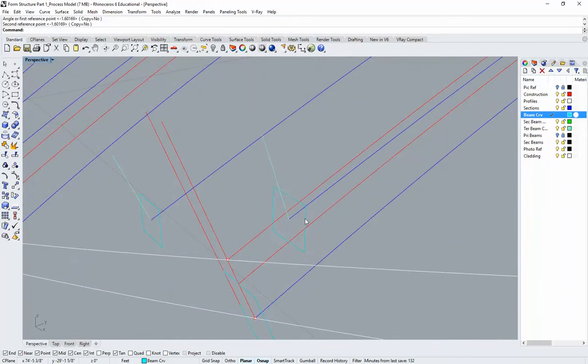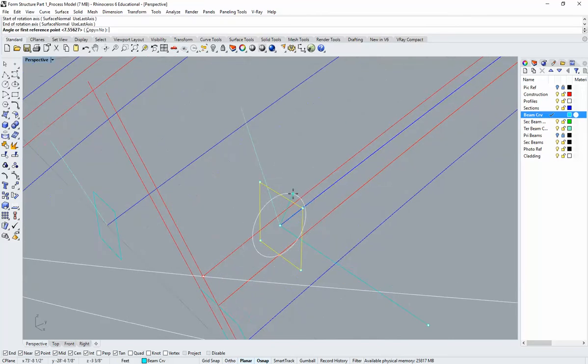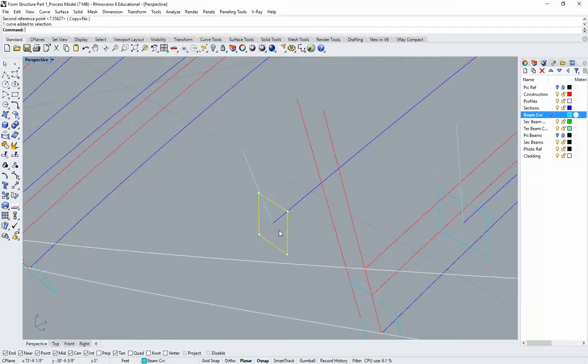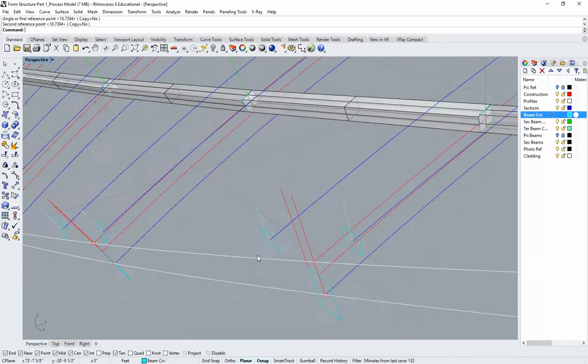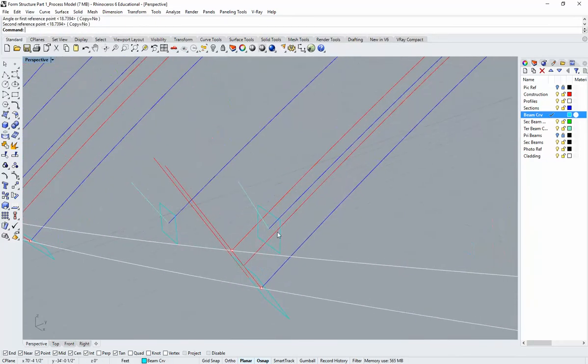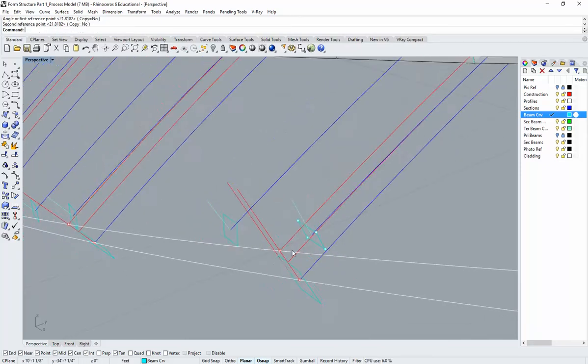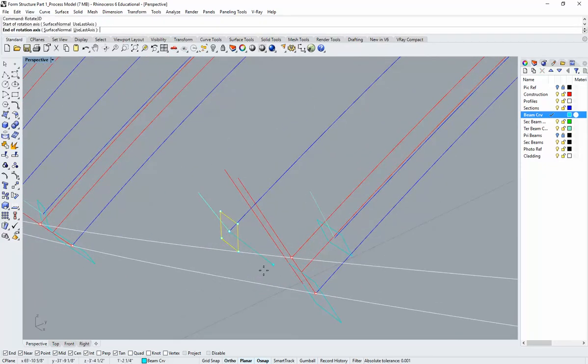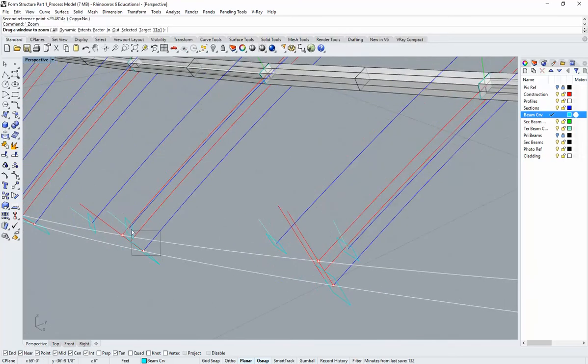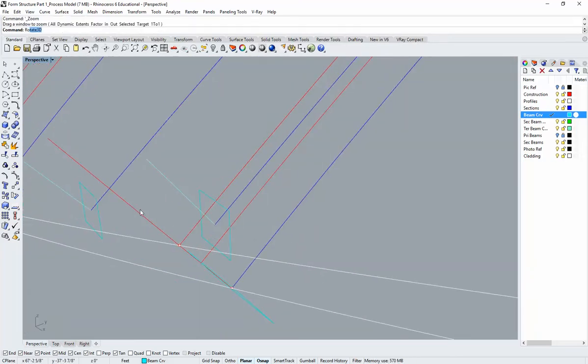Right, so we click it, holding shift in the x-axis again, clicking to the mid, rotating it up, clicking to that construction line so that they're perpendicular to the blue line, so that there's no mitering happening at the end there. They're all cut flat, or 90 degrees from the end of the blue section. All right. This one is easier than some of the other ones we did.